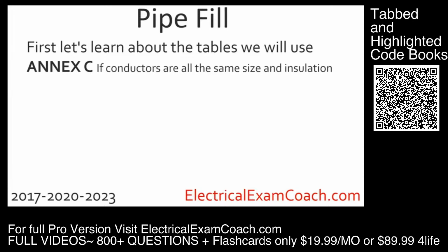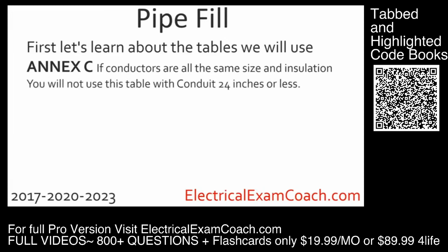If the conductors are all of the same size and insulation type, we get to use like a cheat sheet in Annex C. It's one of my favorite tables in the code book. You will not use this table if the conduit is 24 inches or less. Now the code book uses the term nipples, but I want you to imagine in your mind, anytime the conduit is 24 inches or less, you're not going to use Annex C. You're going to use the method that I'll teach you in lesson 7.2.